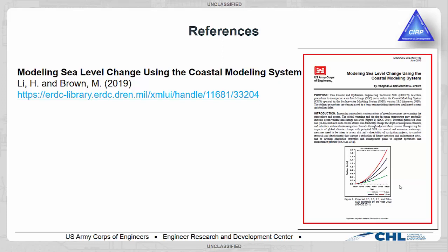In fact, we use a morphologic acceleration factor here. We really run the model for 10 years, and the acceleration factor is 10. So its morphology change is equivalent to a 100-year change. And then on top of that, we put a sea level rise curve from 0, I don't remember which year we started.